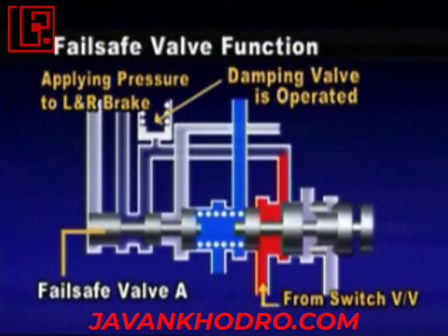When the oil pressure is supplied again to the low and reverse brake, oil pressure is supplied through the damping valve inside the valve body to reduce the slight shock one more time.